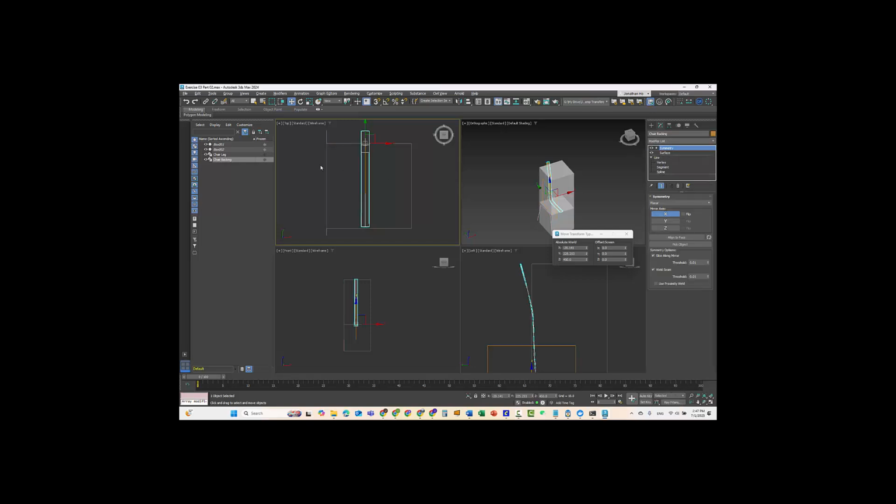Symmetry. If we click on symmetry, you will find that when I expand the sub-selection mode to look for the mirror line and move it, it expands this part here like that. That's how the symmetry would work. But obviously we're not doing this correctly, because that's not how I want it to be. So I need to click on the flip command here to flip it and move this out. This will now allow me to do a symmetry this way.